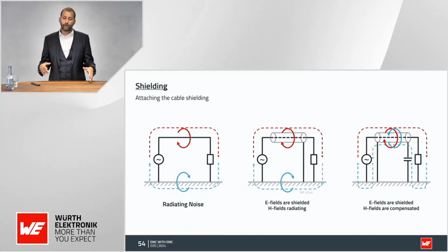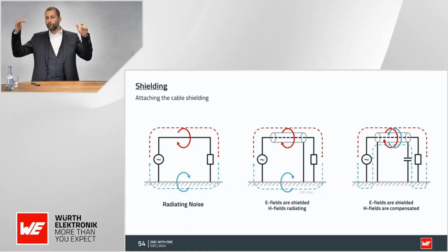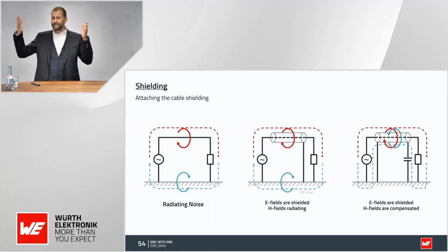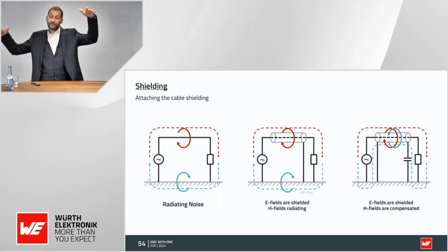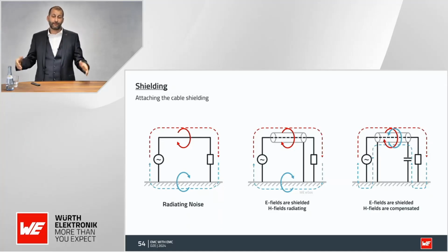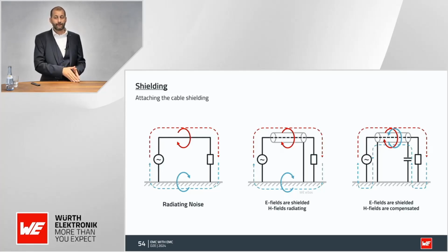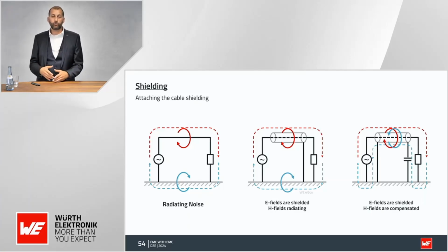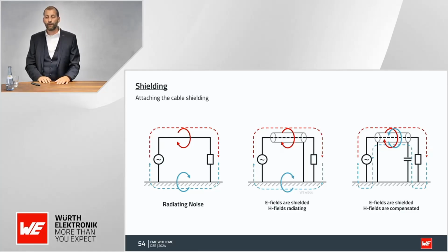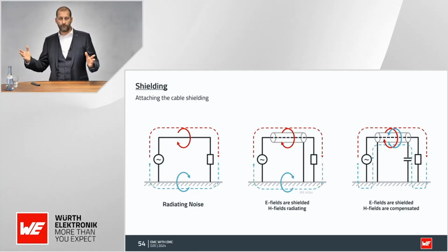So of course, we always speak about ground as this 0 volt potential, but is it really 0 volt? Well, in an ideal world, yes, but electronic engineering is never ideal. So you probably have a difference. A difference in voltage will create a current. So in this case, maybe you should switch to something else. Maybe one-sided shielding is better. Or you go completely glass fiber connections, or what else.